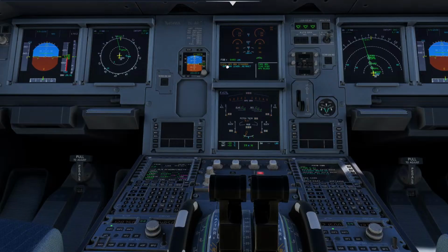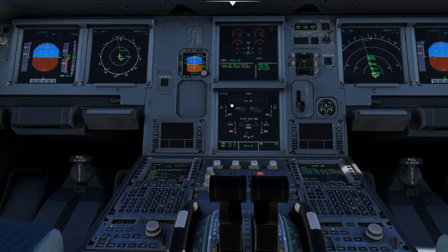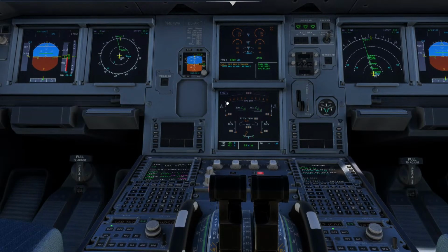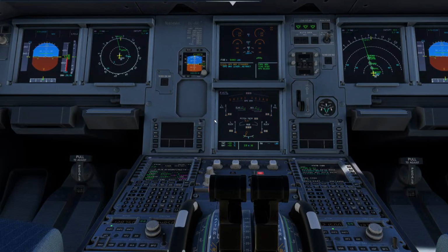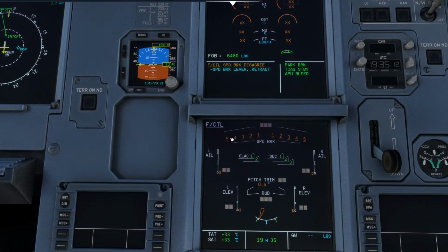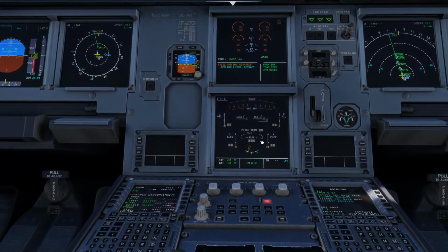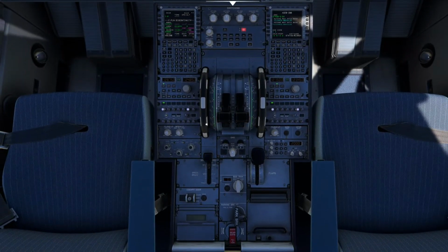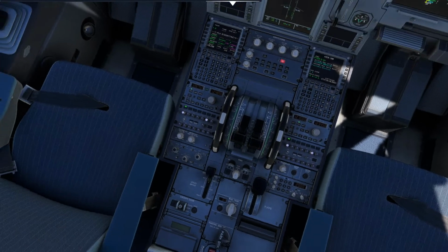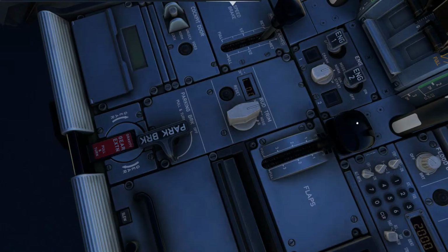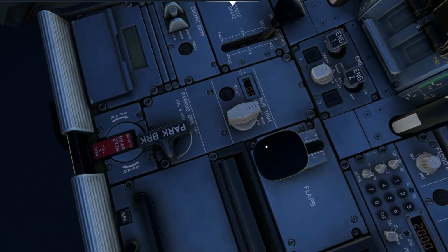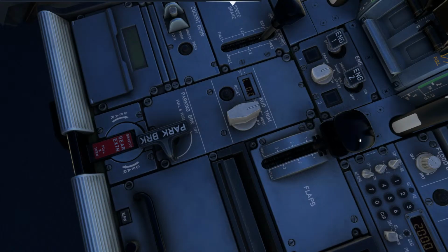And why is it saying it's disagree? Because there's no hydraulic power to the speed brakes. So it's like you got the lever out, but I'm not seeing the movement. As you can see, if it's in amber, you got five speed brakes on each wing, that means there's no hydraulic power. Anyway, sorry, I don't want to get too complicated. So speed brake on the left, flap handle on the right. Airbus is flaps 1, 2, 3, and 4, and you push the button and you move the handle.